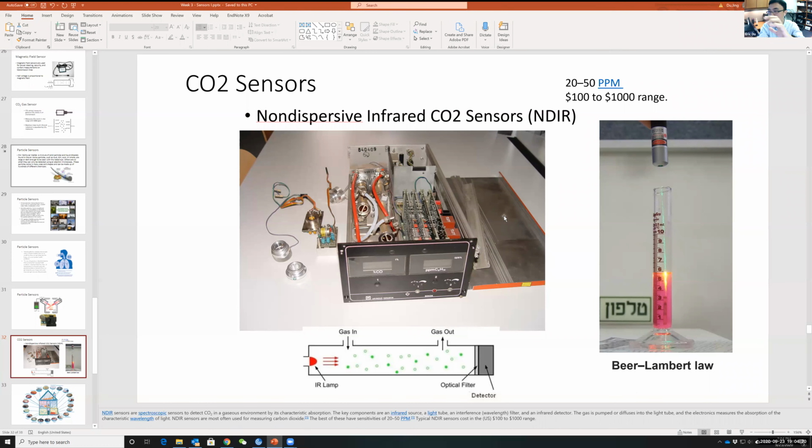Since this can be connected to my phone, it can give me a warning showing the carbon dioxide is too high. So actually this can be used as a building occupancy device. When I have students meeting in my office, the number can hit like 1,500. If there's nobody in my room, it's around 400. When I'm working in my room, it's around 600. When I'm writing papers, it's about 800. So when I'm writing papers, I'm consuming more oxygen and releasing more carbon dioxide. So yeah, just some quick examples of sensors.